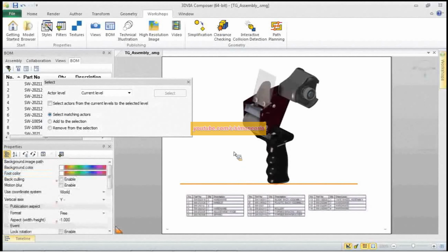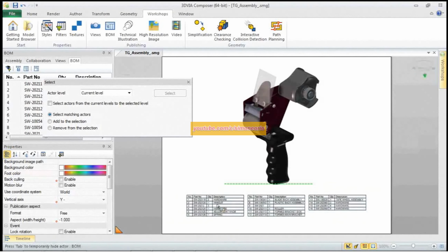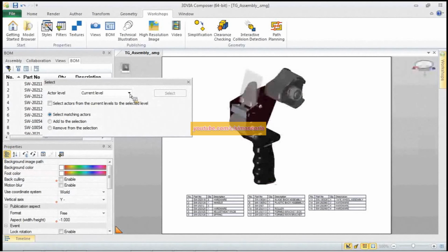And then we can also balloon out the assembly as well. And what's, again, nice about this is that you can see in the description here on the parts list, we're pulling in all the metadata associated with the CAD files. Let's go ahead and, as I said, let's balloon this out.